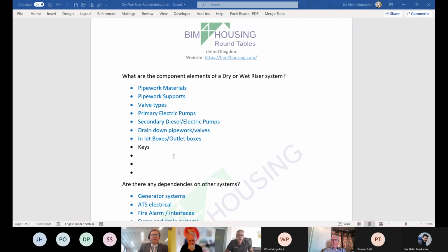Crikey! So by opening the door to the dry riser, you're creating an opportunity for fire to go up to the next floor. Is that what you're saying? Yeah, correct. It depends, because there are different arrangements for this. You've got pressure differential systems, and whatever you're doing, you've got different arrangements you can have. Sometimes in residential they're in the staircase. Sometimes they're not, they're inside the corridor, rightly or wrongly. Sometimes they're inside the firefighting shaft. It all depends on where it is, because the minute you go to plug in the device, and sprinklers are no different, if you go to the valve to turn them off, you can't have a situation where you're open to the levels above, because you're breaching the compartment the minute you open the door.